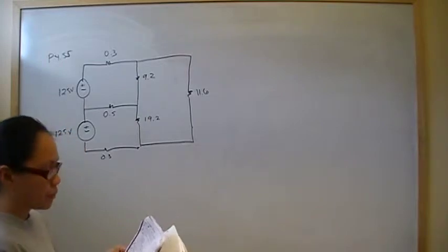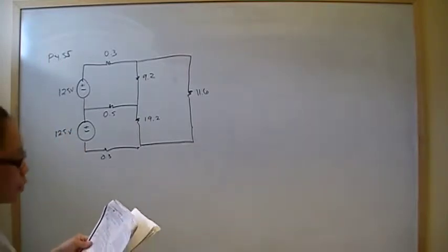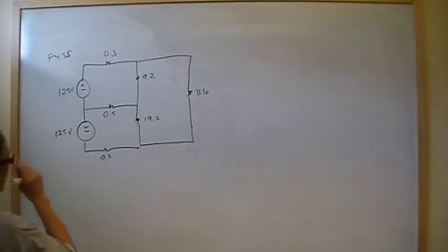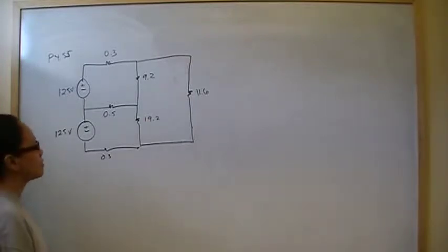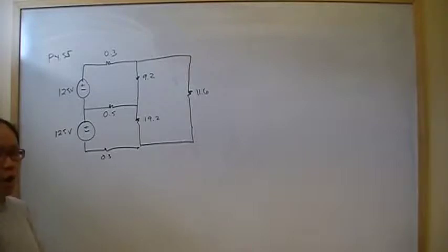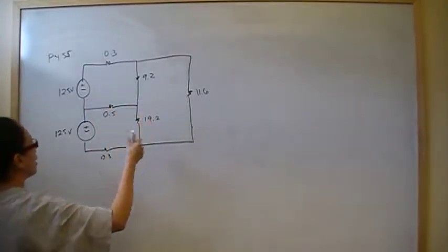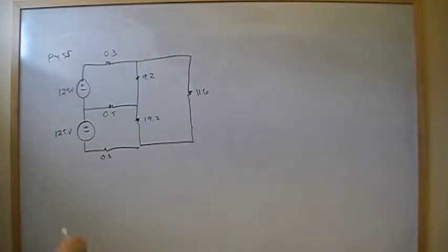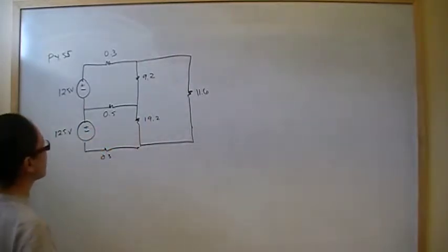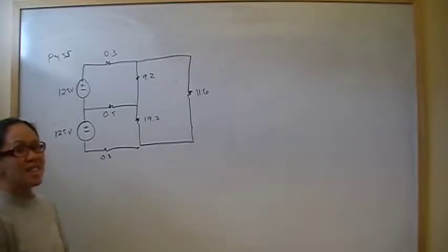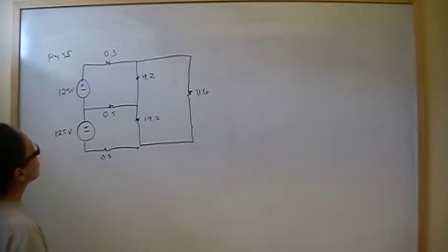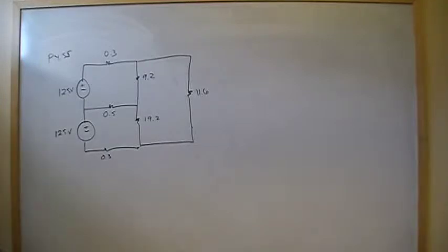Question A. So which circuit analysis will you use and why? First of all, let's see how many unknowns we have. With the mesh method, we clearly have 3 meshes, 1, 2, 3. And just doing a preliminary look at what kind of equations we'll get, it looks pretty straightforward. So the mesh method has 3 equations and 3 unknowns, and they look to be pretty straightforward equations.